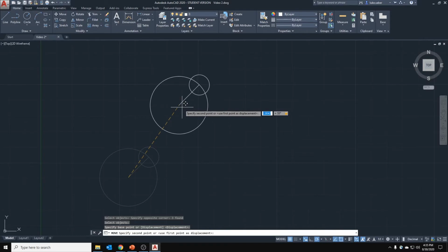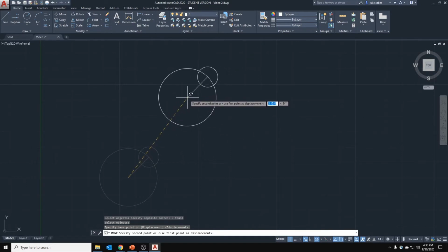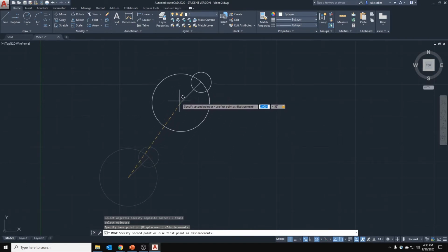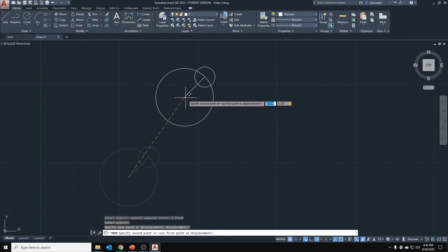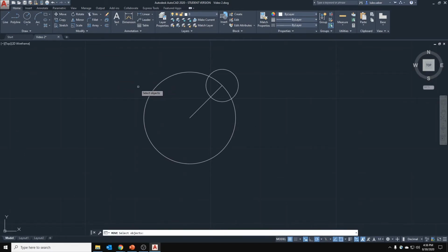And this is something super useful. If you want it to be exactly at 55, you'll notice on that side piece there that it's got a little lock on it. That lock is helpful because now it's locked at 55 degrees. You can go back and change it, but once you've entered one and you go to a different section, for example the length, now that's constant. It's kind of held in place, so you don't have to worry about it moving all over the place. So we'll do 55, and then I'm not really going to be particular about the length, so I'll just click it. So we have just moved, and there's nothing else super crazy about that.